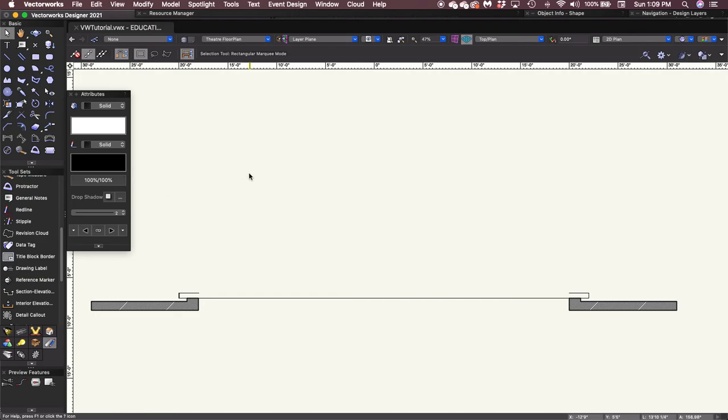Then I need to activate my text tool. It's in the basic tool palette. It's right here. Its keyboard shortcut is the number 1. So I'm just going to hit 1. It'll give me a cursor. Now wherever I click is where I'm going to be able to start typing. So I'm going to click once and give it the letter Shift P for a capital P, and then hit escape once.